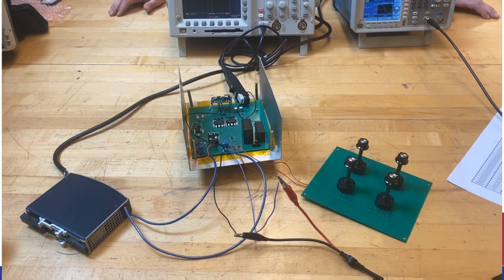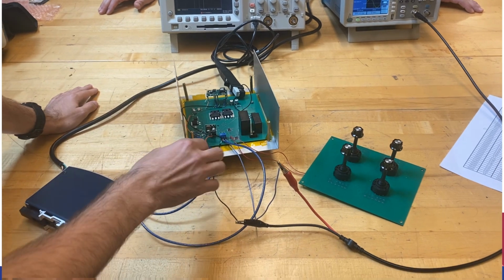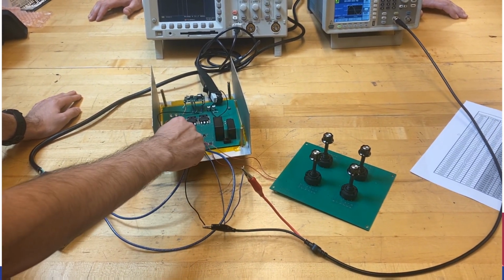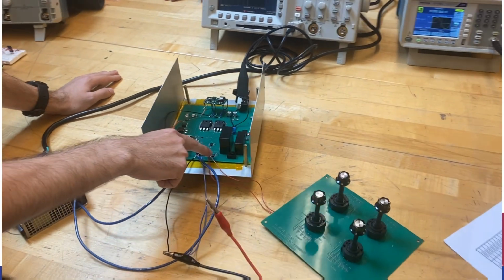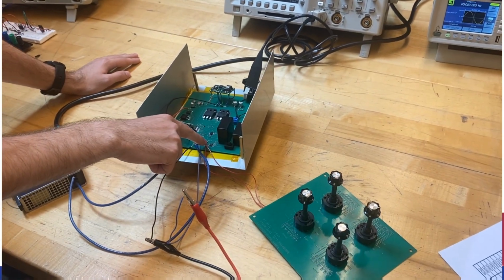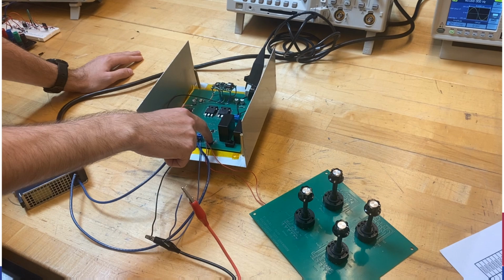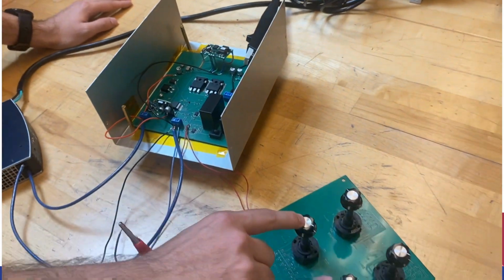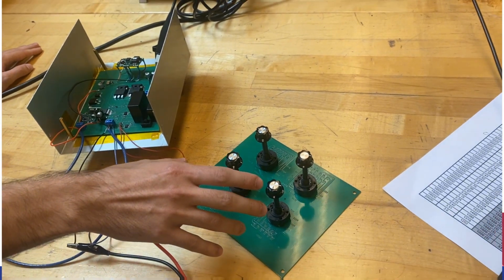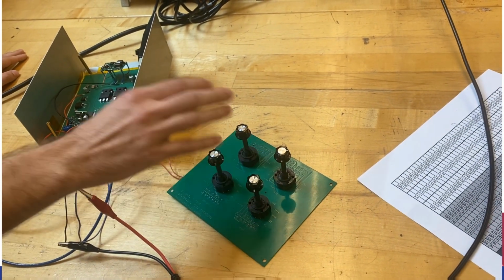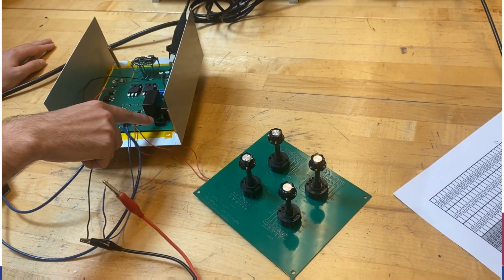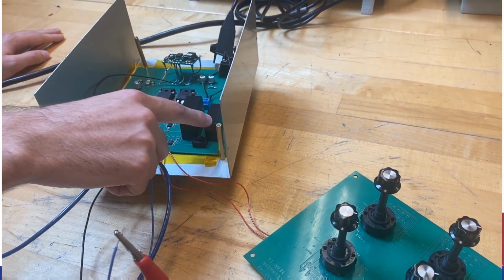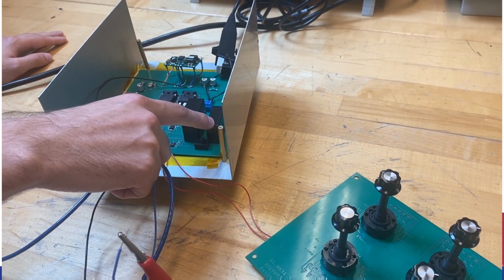Okay, so feeding from there into our first input circuit, we have this input terminal where our expected Rogowski coil integrator signal is going to go into, and that will feed into the primary amplifier and the active integrator. They're all in one package, and these two wires feed onto this board, which allows us to select those switches as mentioned in the slides. So that allows us to select the resistor value, and this switch allows you to select between the 50 hertz and the 60 hertz capacitor as needed based on your input signal.